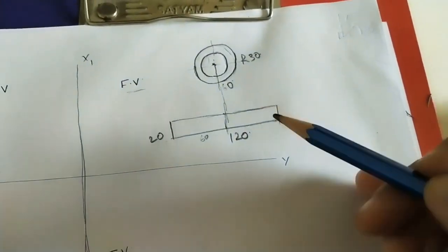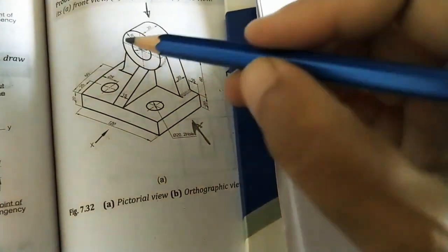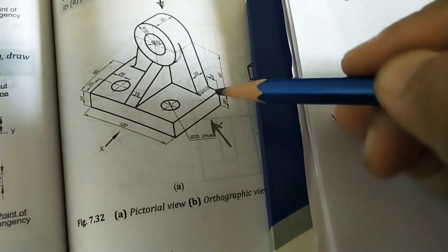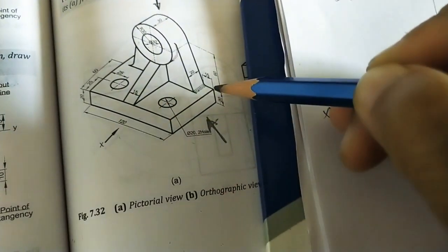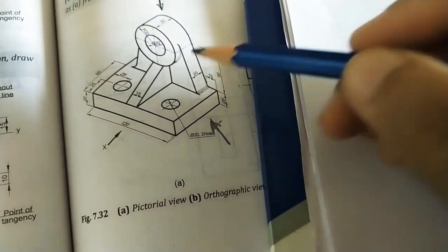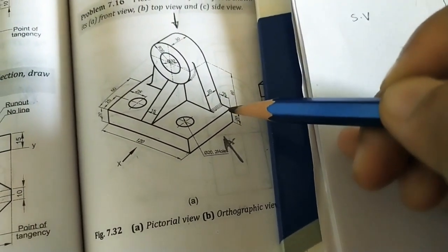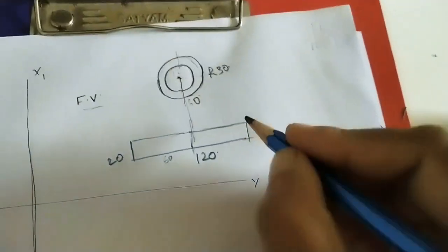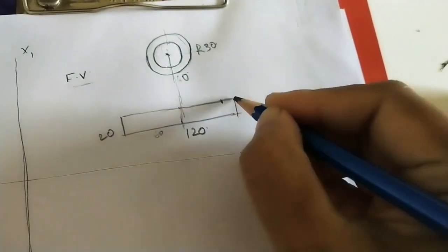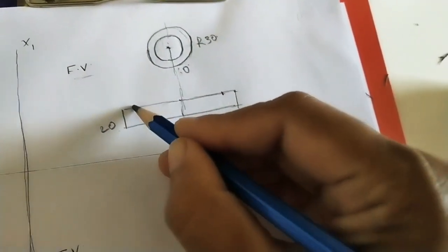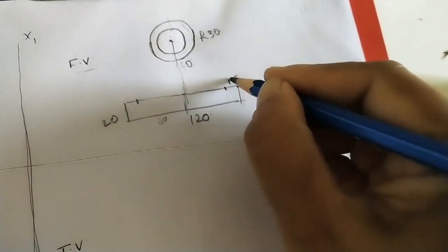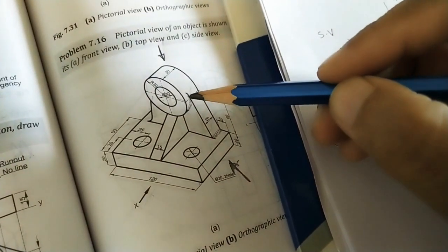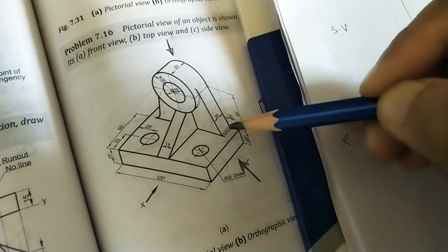Same thing I did here. After that, here we can see the slope part also. In this front direction we can see this slope and this slope. Now this slope, we can see 15 mm from this direction, this side 15 mm, this side 15 mm, because it is a symmetrical diagram. So in this 120 mm, take this length 15 mm this side and 15 mm this side. From this corner take 1.5 centimeter and mark one point. From this side also mark 1.5 centimeter, or 15 mm.